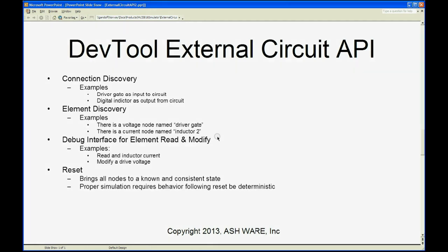Next is the reset interface. Although the reset interface seems like it is simple, it is particularly important that all internal states be properly initialized to provide repeatable simulation runs. There is nothing worse than a simulation not acting the same on every run except perhaps boiled spinach. Such problems are always a result of incomplete state reset.